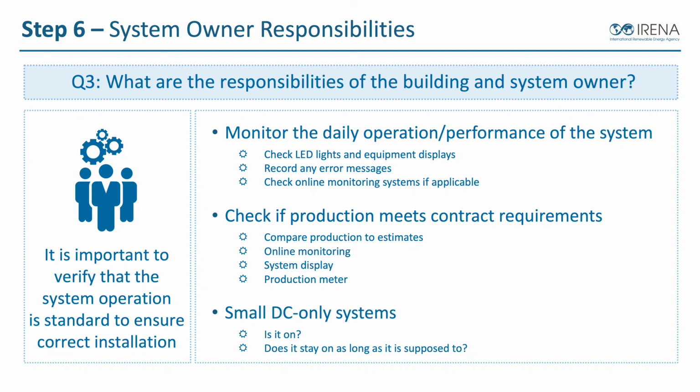Do the lights come on when they're supposed to, and does it stay on as long as it's supposed to? Do the lights come on when the sun sets, yes or no? Do they stay on for an hour or 3 hours or till dawn? Whatever they're programmed to do, are they doing that? Sometimes that's about all you can look at.